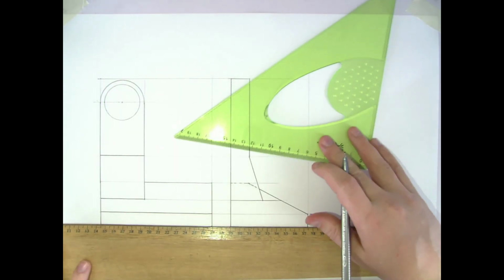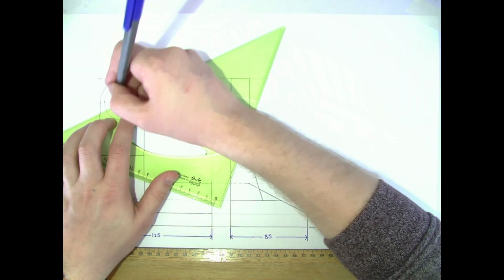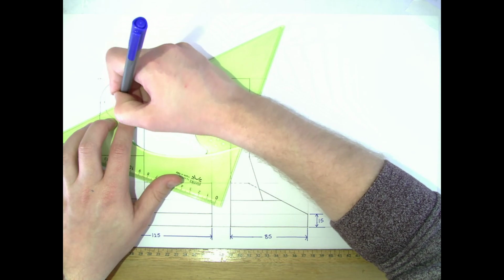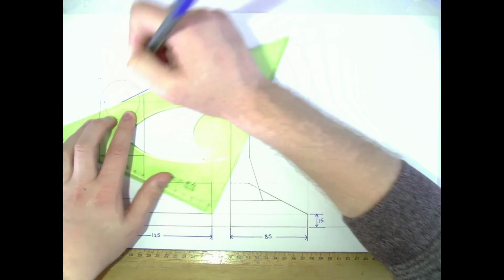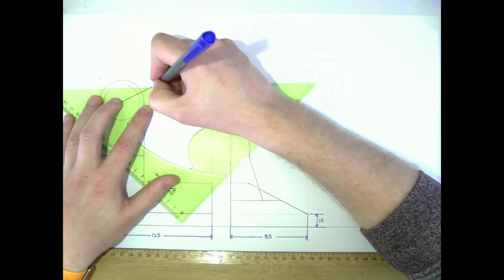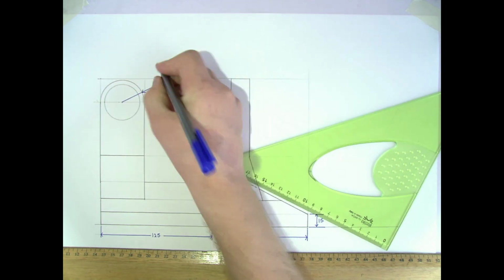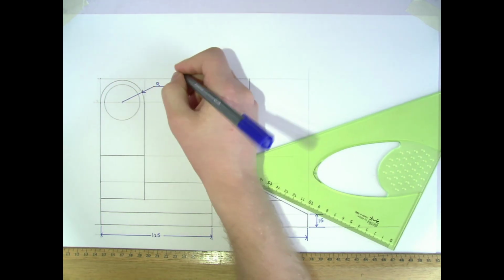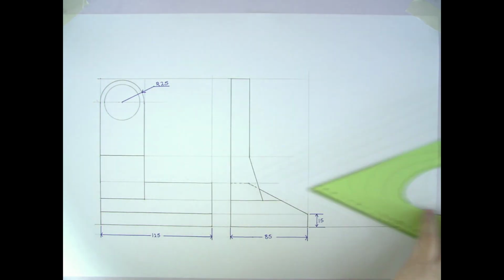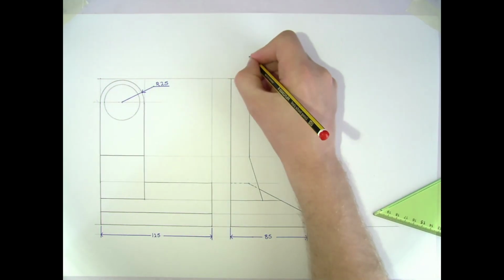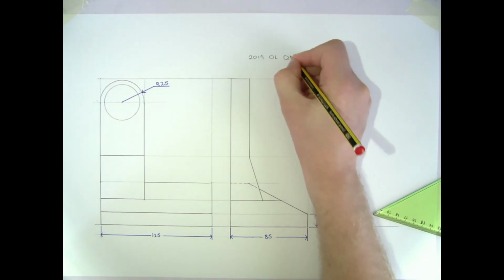So I might take the distance for the radius. So if it's a radius, it's a line drawn from the center. You can extend it out that way, and you can put a horizontal line on it. So from here, arrow touching off the outside, R 25. And there we have it. That completes 2019 Ordinary Level Question 1.